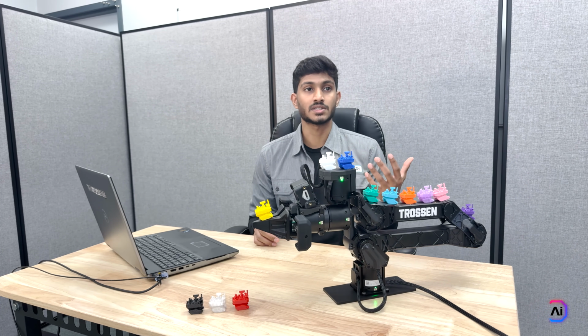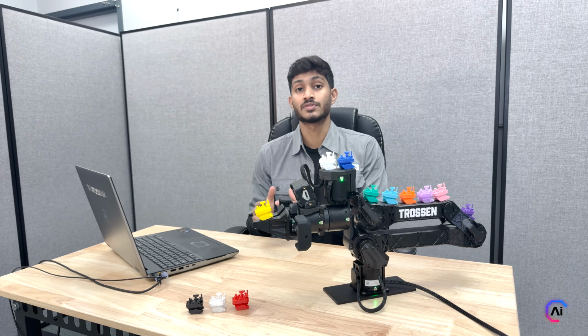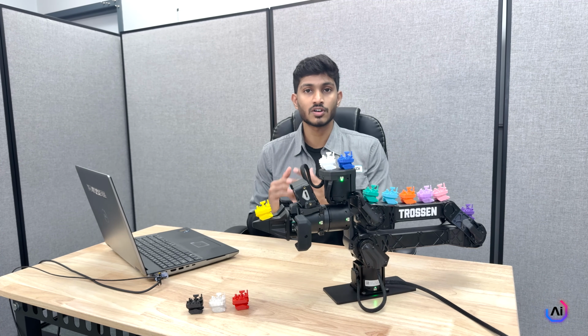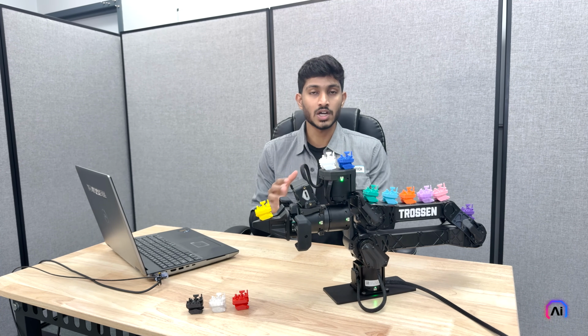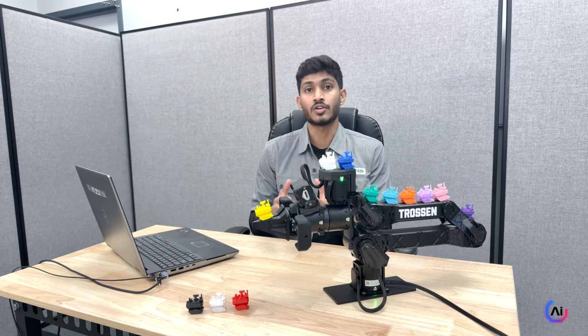Again, a quick reminder, these gains are for demonstration purposes only. Improper tuning can lead to unstable arm behavior, so always test carefully. All these scripts like Cartesian position, Cartesian velocity, Cartesian external efforts are available out of the box for you. You can find them in the official Trossen ARM repository, and they are well documented so that you can change them according to your use case. This new Cartesian control support makes high-level behavior much easier to implement, especially in learning-based or reactive control scenarios.